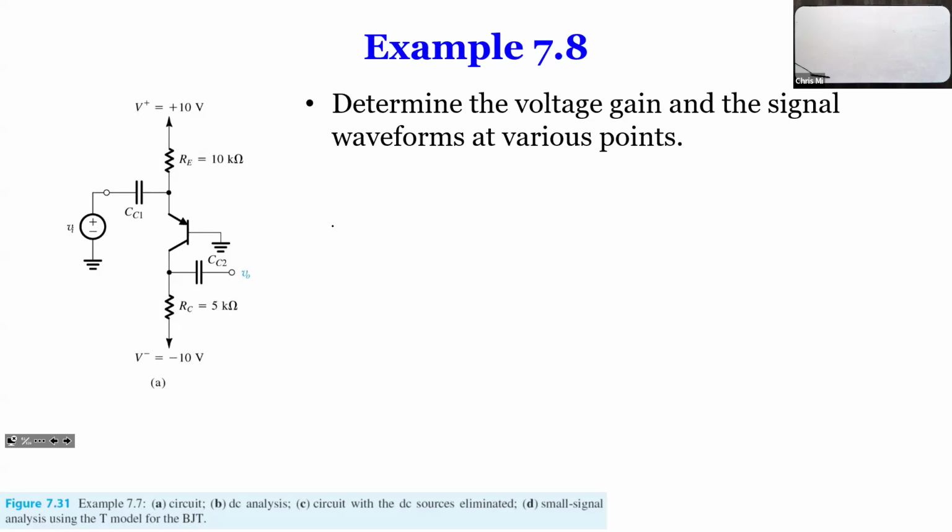But in this case, if you look at both the top and bottom, the emitter and the collector both have resistance. So naturally, you would use a T model. And again, I want to emphasize, there's nothing wrong with using the pi model. It is just going to make your life a little bit more difficult. You can still solve it. It's just that the equation becomes more complex and it takes more time to solve the problem. You might make a mistake in the middle when you manipulate the equation. So using the T model in this case will make it simpler. That's all I want to say.